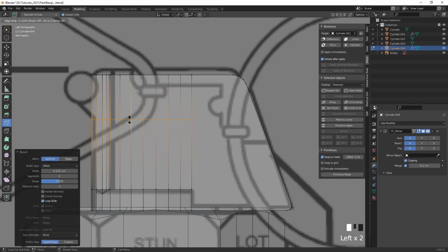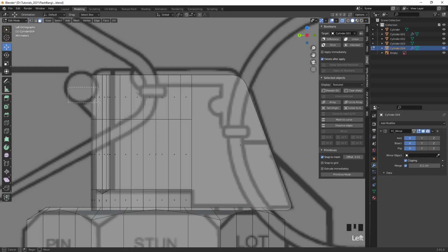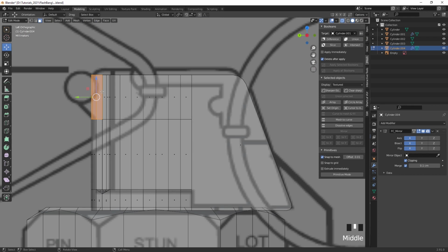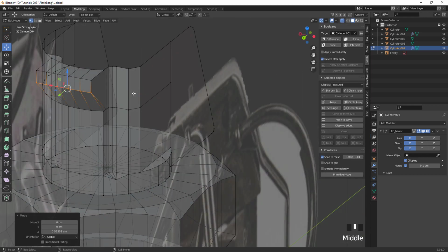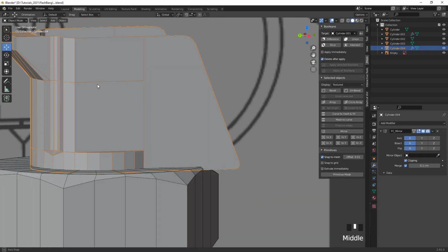I'm gonna use the loop cut tool and add an extra edge loop here. And then while we are in our face mode, I'm gonna select these faces and extrude them out. And I like to snap it back then. And I'm also gonna align it here, S, Y, and 0. And then bring up these vertex points here. So that way we have this shape here already formed.